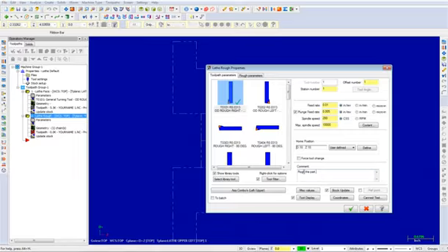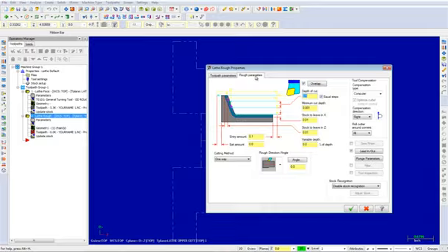Now, select the Rough Parameters tab and make any necessary changes as shown. Change the amount of stock to leave in both X and Z to 0.005. I will now explain the parameters on this page.